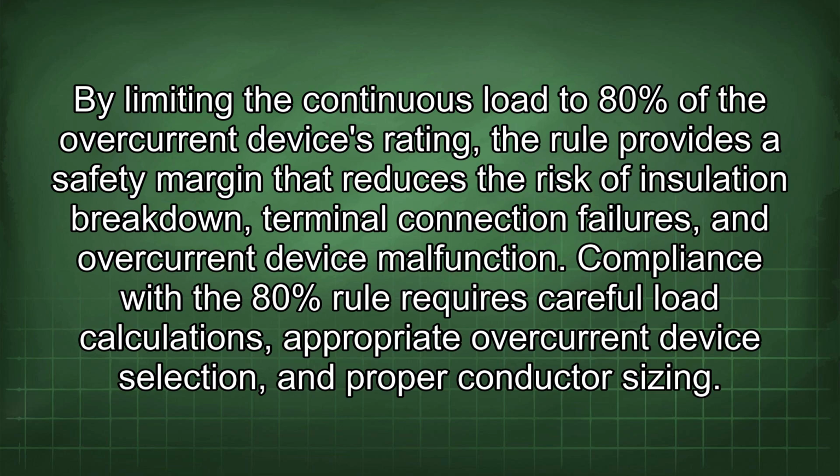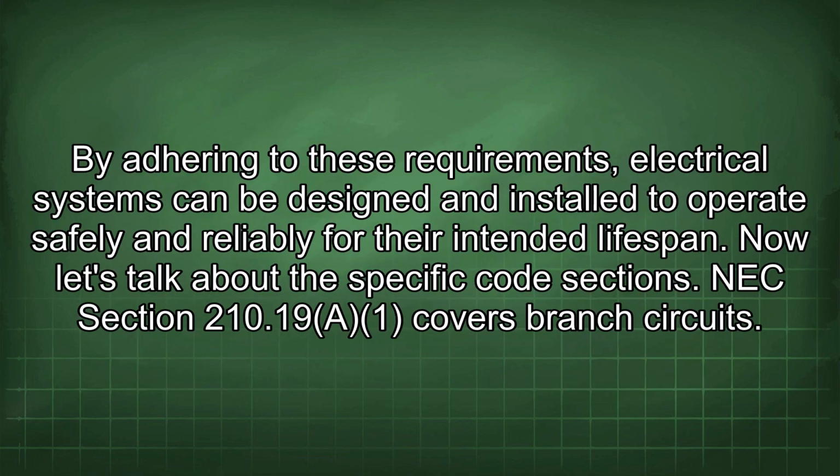Compliance with the 80% rule requires careful load calculations, appropriate overcurrent device selection, and proper conductor sizing. By adhering to these requirements, electrical systems can be designed and installed to operate safely and reliably for their intended lifespan. Now let's talk about the specific code sections.